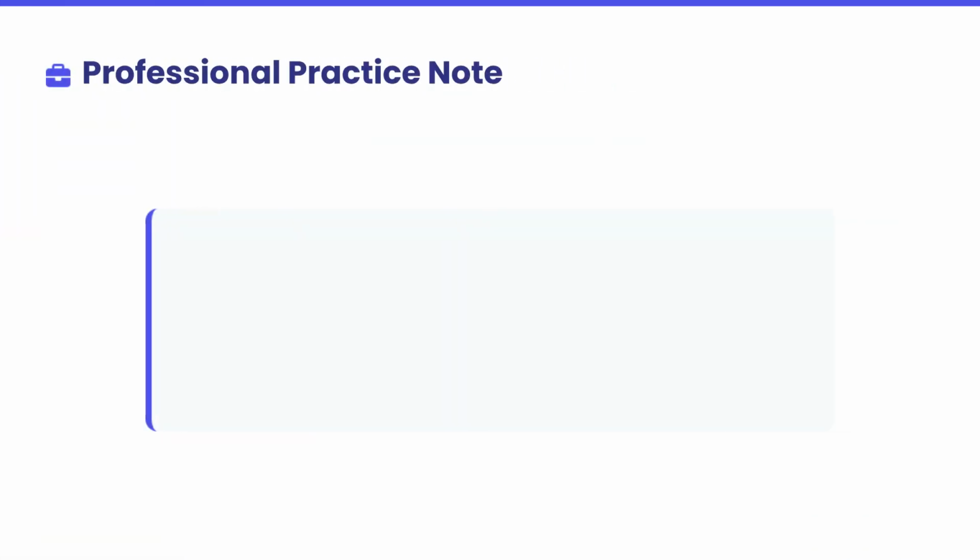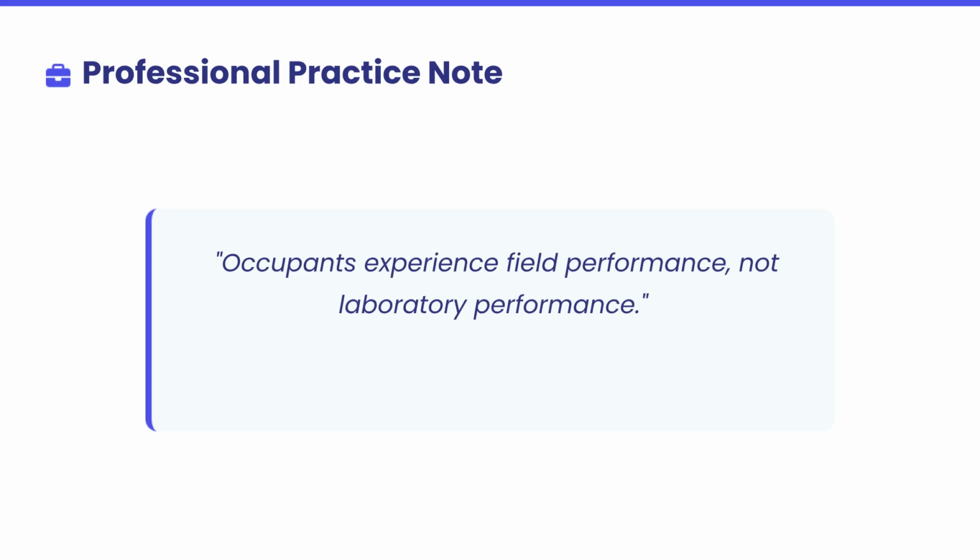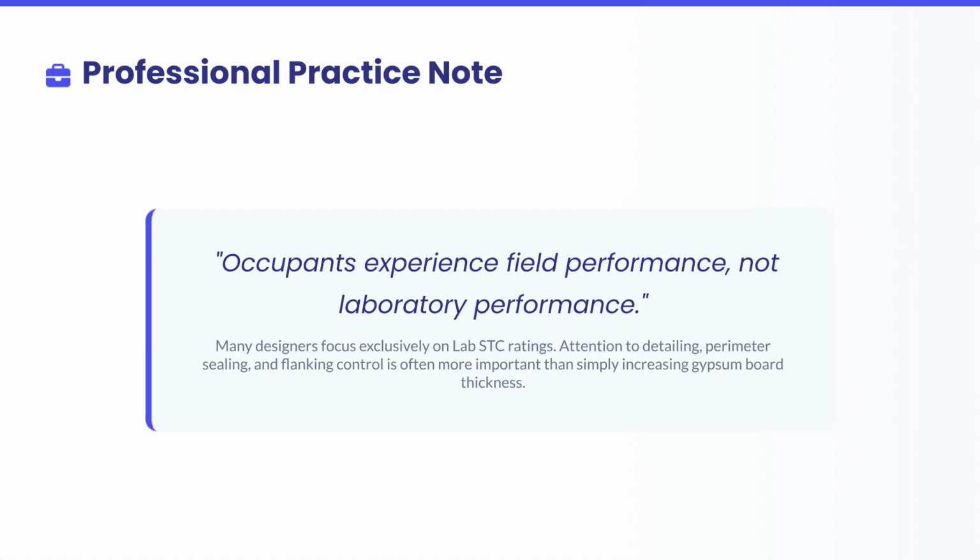As a professional practice note, remember that occupants experience field performance, not laboratory performance. Focusing on detailing, sealing, and flanking control is often more important than just increasing gypsum board thickness.